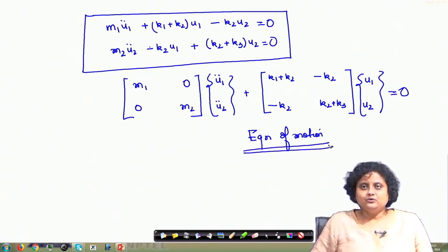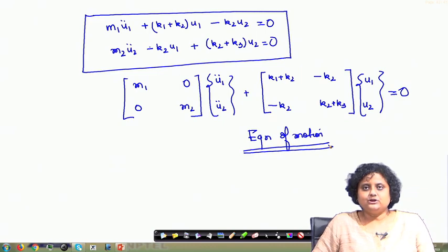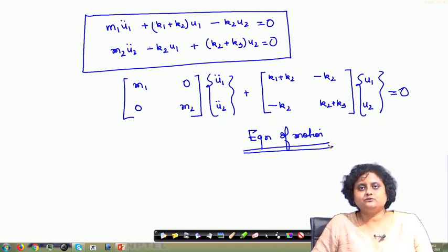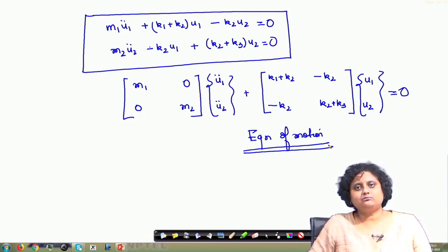So, by using the Euler-Lagrange equation and the expressions for kinetic energy and potential energy of the 2 degree of freedom spring mass system, we can obtain the equation of motion. You can check for yourself. This is the equation of motion that you will get by solving the system using the conventional dynamic equilibrium method or using D'Alembert's principle, and they match exactly.